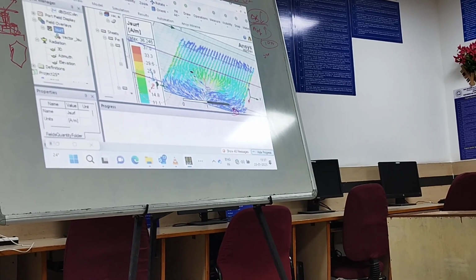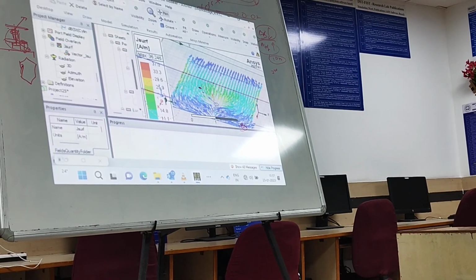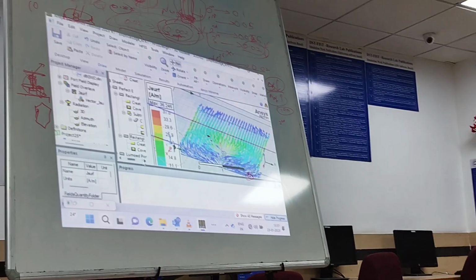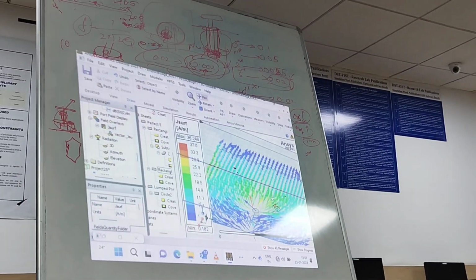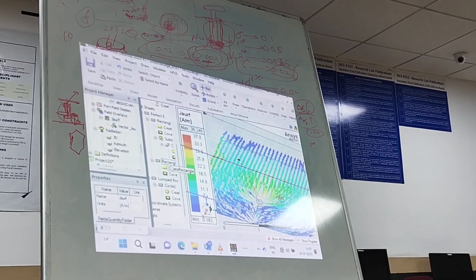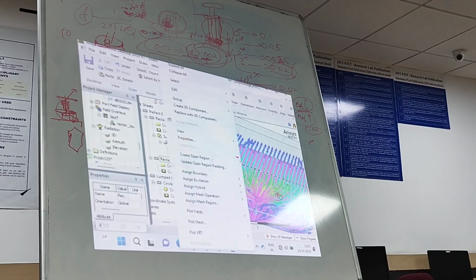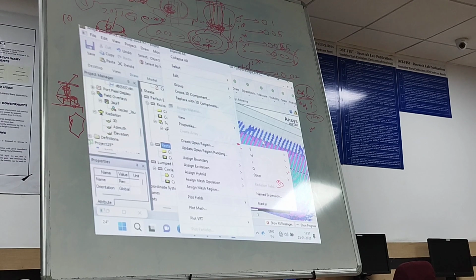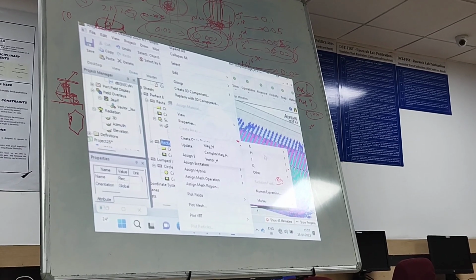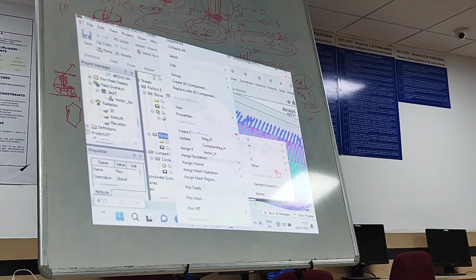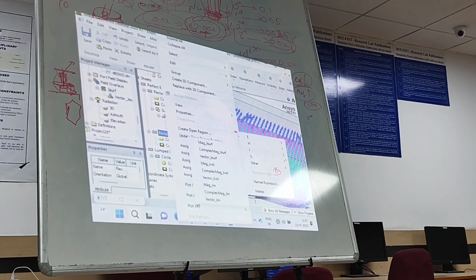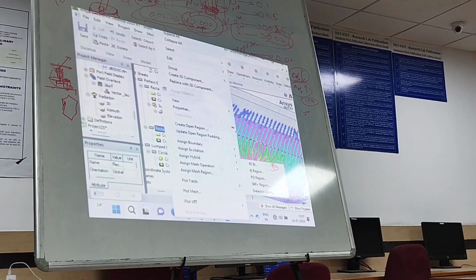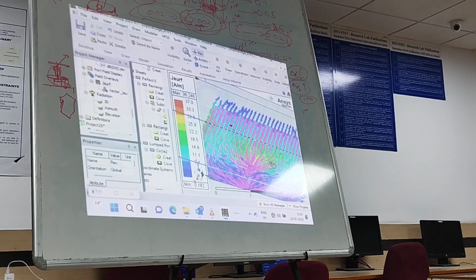So here, similarly, you can select the perfect E, which is rectangle 2. Progress. So again, once you right click on that particular geometry, go to assign field, you can go for again E field and H field. Mostly it will be 90-degree perpendicular to each other. So if E field is along y axis, H should be along x axis. So in that way you can just go ahead with this analysis.